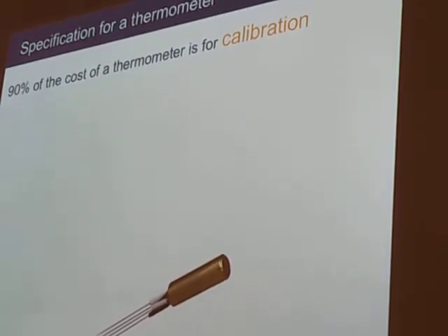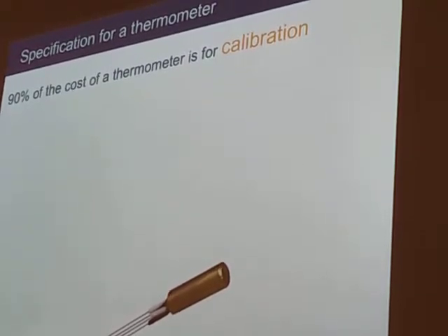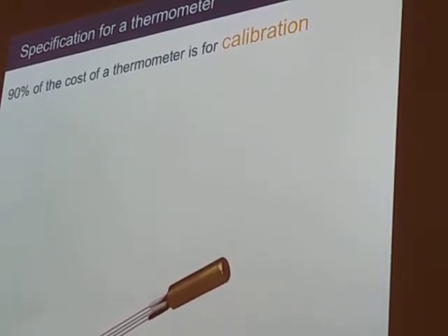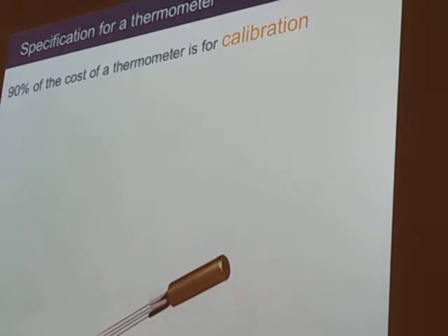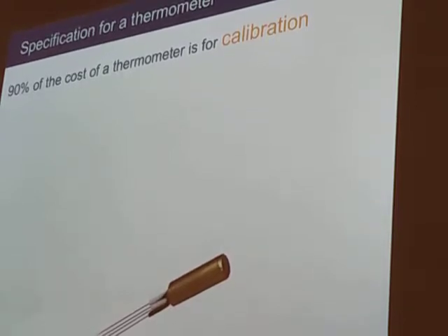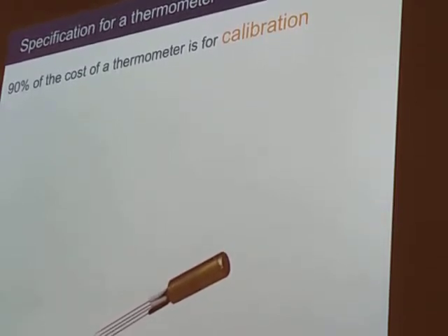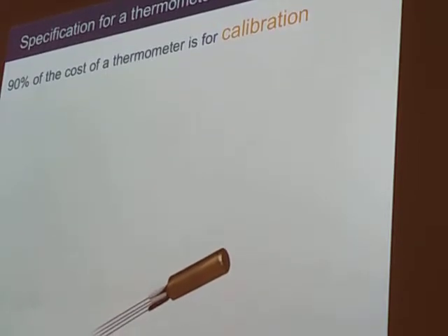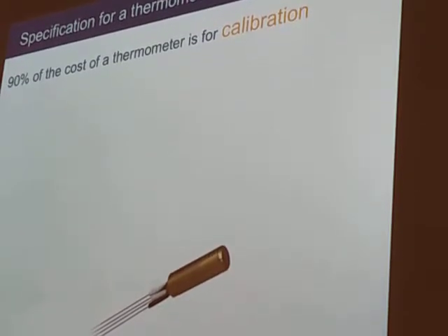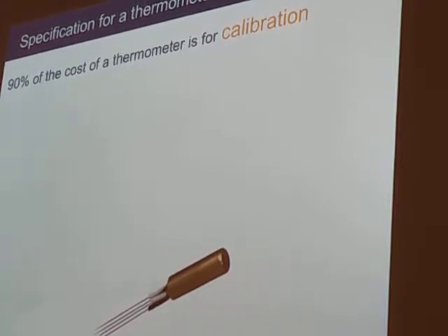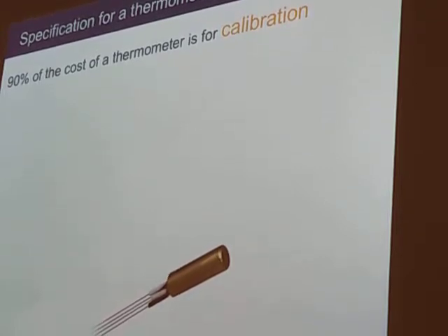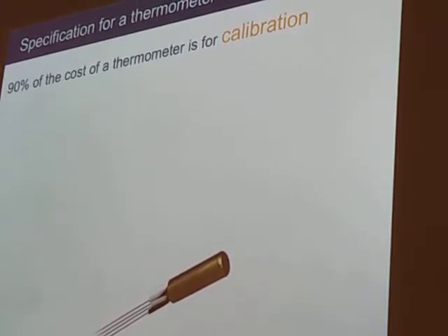And that means that when you bought a thermometer, somebody had to go away, sit in a lab with a calibration thermometer, and spend a lot of time plotting for you the curve of resistance with temperature. About 90% of the cost of these thermometers is in that calibration. So we were wondering, perhaps we might be able to use machine learning to propose a new thermometer material that has a simpler electrical resistance with temperature behaviour, and so it's going to be cheaper to calibrate.